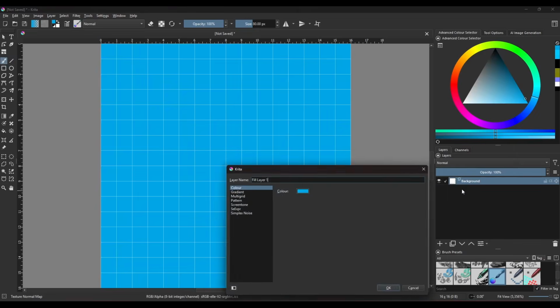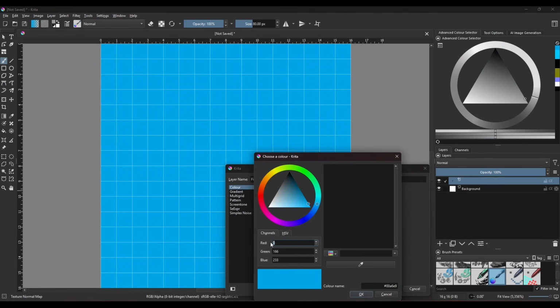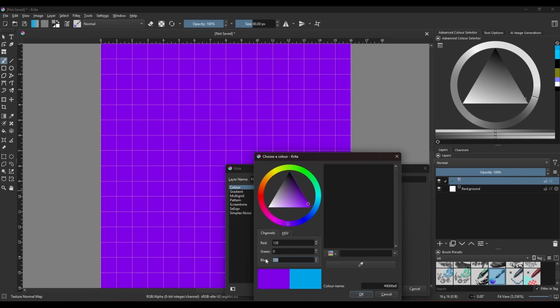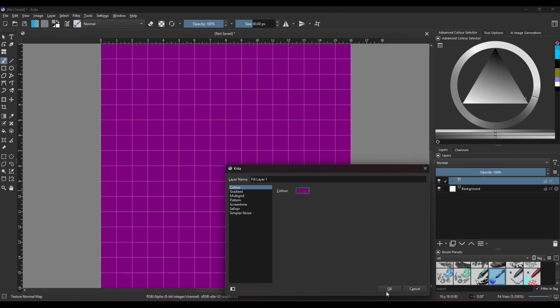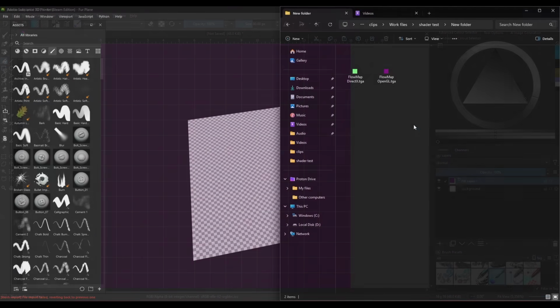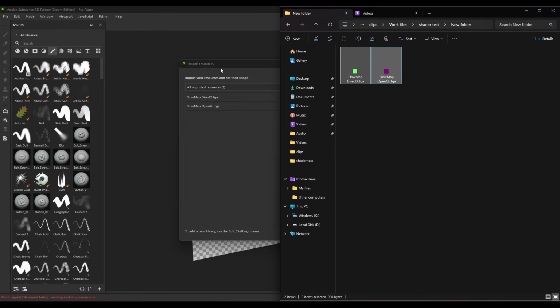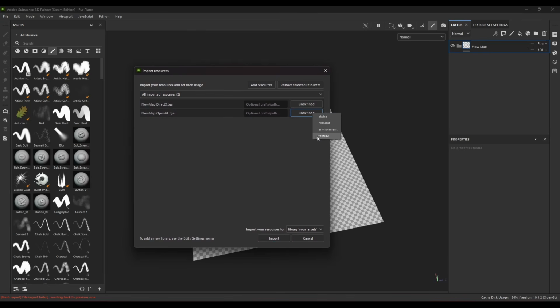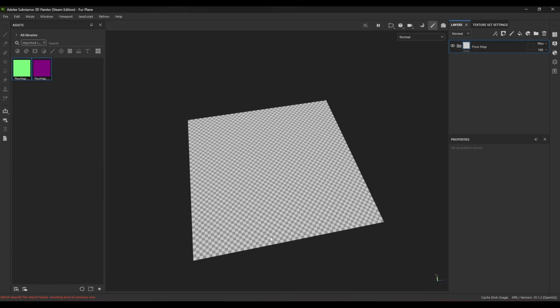If your workflow uses OpenGL normal map conventions instead, simply invert the green channel, which gives a value of 0. I import this texture into Substance Painter, and I recommend keeping it in your library permanently, so you do not need to recreate it every time.